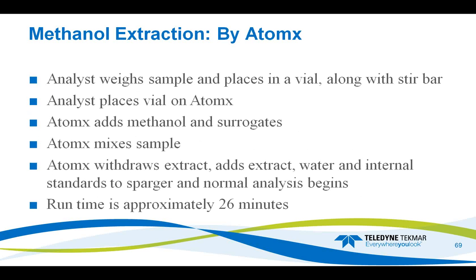With the Atomx, it does almost all of that for you. At the time of collection, the sampler would assure that 5 grams of soil were collected into the vial. The stir bar would be added at that time, the sample capped, and then it's never opened. It's never uncapped from that point forward. So there's no concern of loss of volatiles when opening the cap to add the methanol.